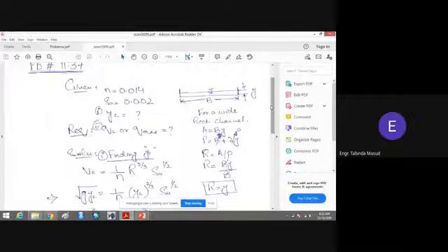So this is given. We have a wide rectangular channel for which this is the width of the flow, this is the depth of the flow, and Manning's roughness coefficient is given 0.014. Slope of the channel bed is given 0.002. This is the critical depth of the flow, and we have to find the critical unit discharge, which is actually the maximum discharge.